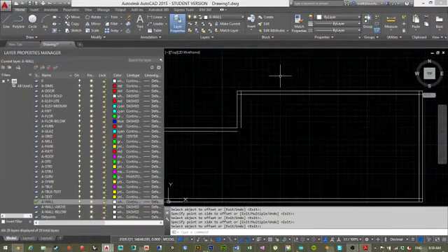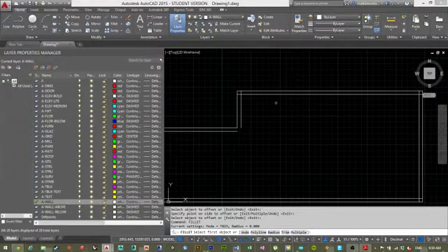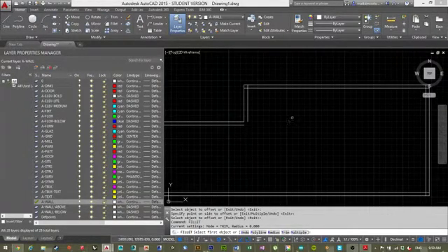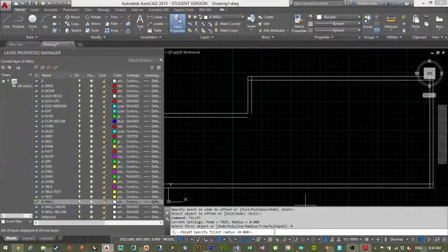But from there, I just use my fillet, just F-I-L, or just type out the whole word. And you'll see the options that come up, radius. The important ones are radius and multiple. I think radius, for some reason, always is on a default of some little number, so I would check that. What that's doing is, if you want a rounded edge, it will round the corners.